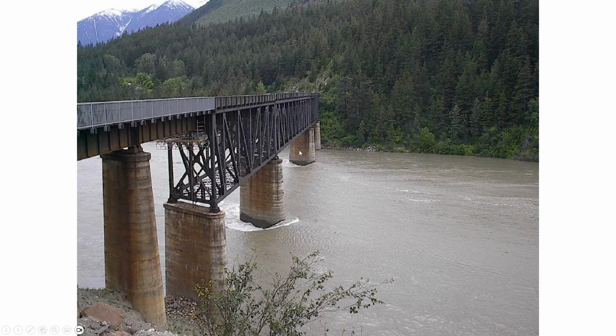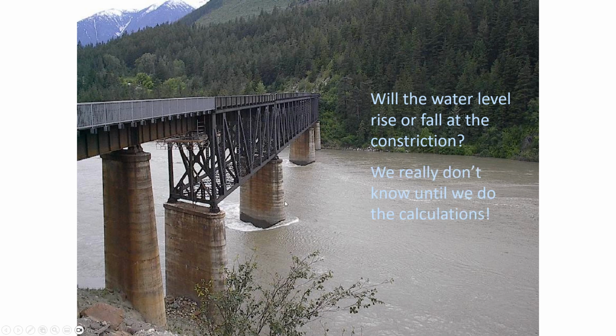But the question is, when the water goes through there, will the water level rise or will it fall at the constriction? Like, will the fact that we have less flow area cause the water to be higher or lower in the vicinity of those piers? And the answer is, we don't know until we do the calculations to determine whether the flow conditions were supercritical